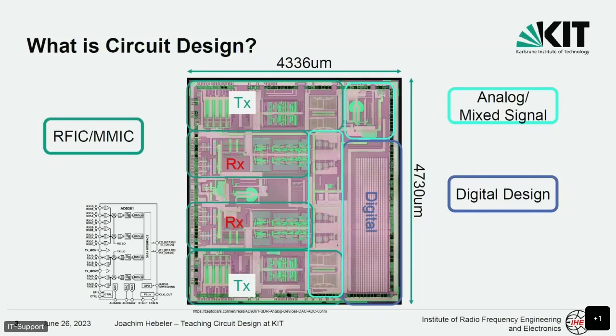But we also have all this RF domain. And if you look at the left, the RF part is more or less the biggest part of this chip. However, on the RF part, there are probably like 20 transistors, or with all these front ends, 100 or 1,000. So we don't talk about circuit complexity, but we talk about layout complexity. People have to think about how they set up all these layouts, because RF means we have to take all these little shapes into account for what we are doing.